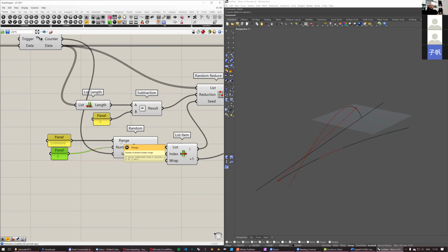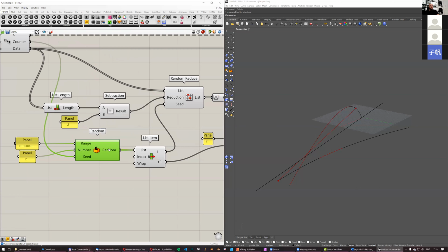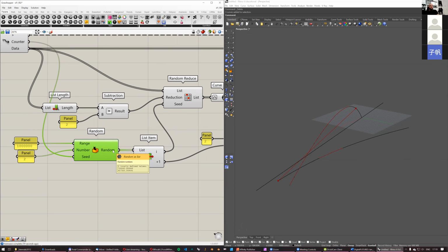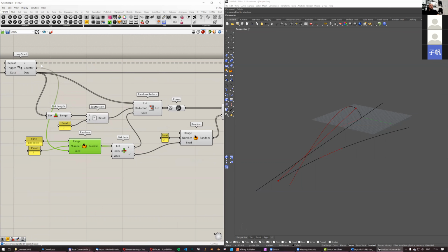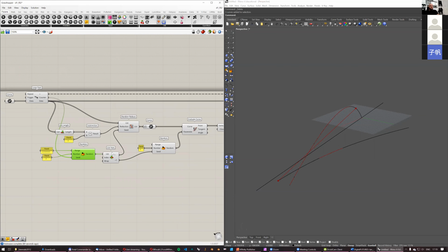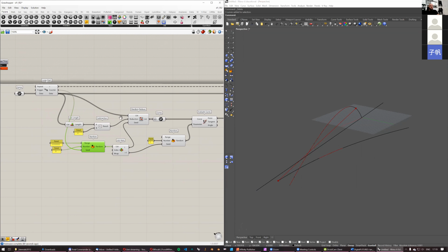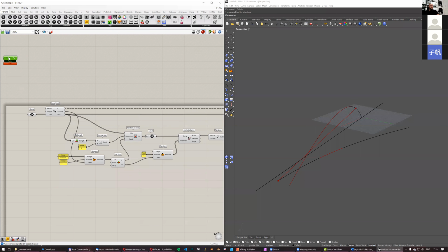And the thing that Grasshopper does is it automatically converts one data type to another. So now it's converting the number into the domain. That happens so that the number that I specify is the end of the domain, and by default, the start of the domain is 0. So now this is picking 2 random numbers between 0 and 1 million, and they are used as random seed. And in each repetition, the random seed will be different. Okay.